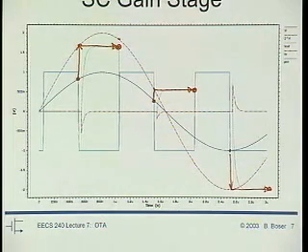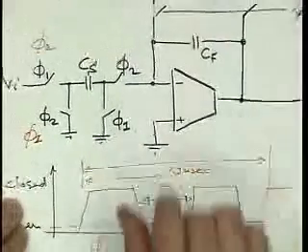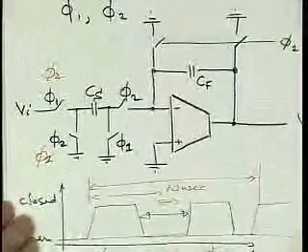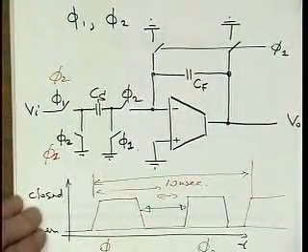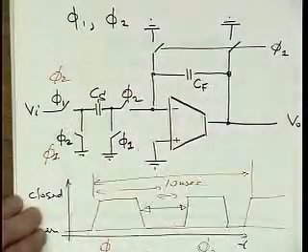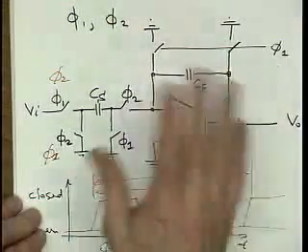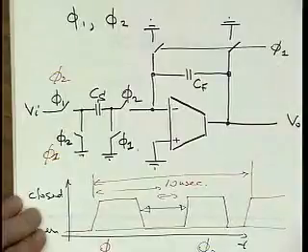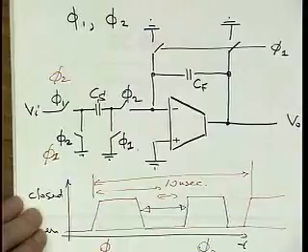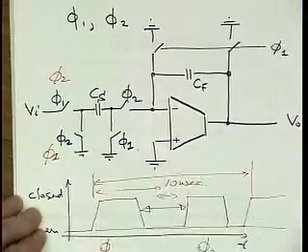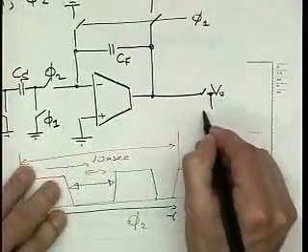Now we have the next interesting thing to look at, of course. Our favorite topic is noise. What's the noise implication of this? Well, the feedback network, all capacitors, right, they ought not to give noise, but now we know better, right? We drive them for something, we have these switches, and altogether we get noise, right? So we get noise from our sampling capacitors, from our feedback capacitors, and then we also, of course, get noise from the amplifier itself. And for that, I'm going to extend my circuit a little bit.